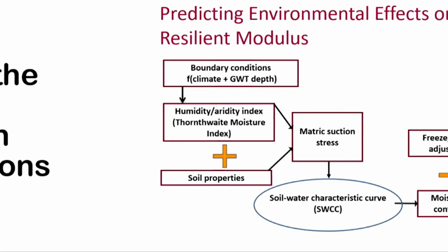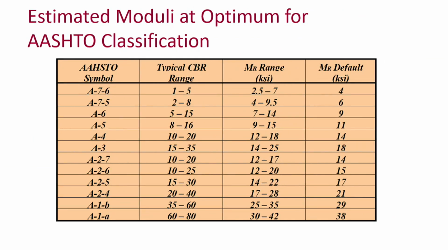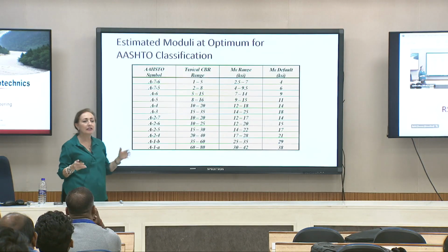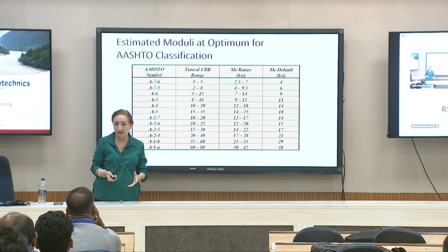All right, so you get the stiffness of the material by calculating this one, modified by the resilient modulus. And the typical resilient modulus from the laboratory at optimum condition are given in these tables, right? So I gave you a couple of soils, and you can just have the resilient modulus that we got in the lab, that you also learned how to get, right?